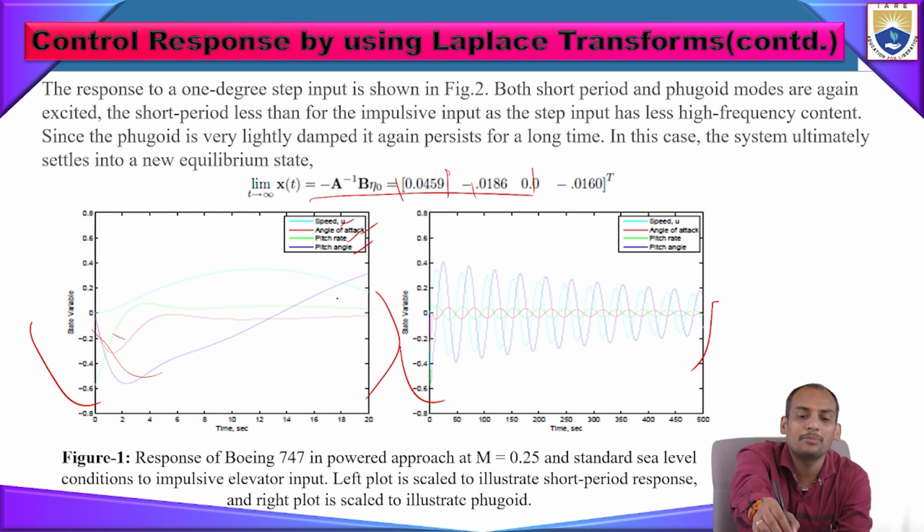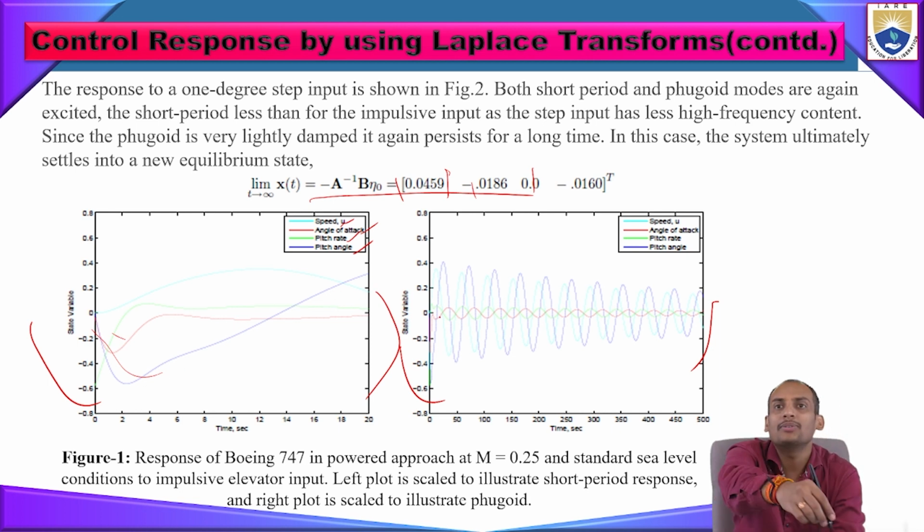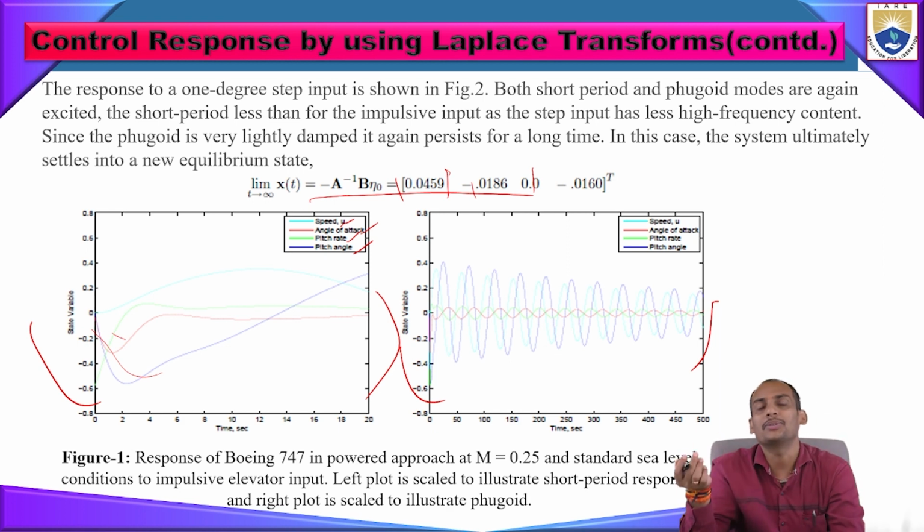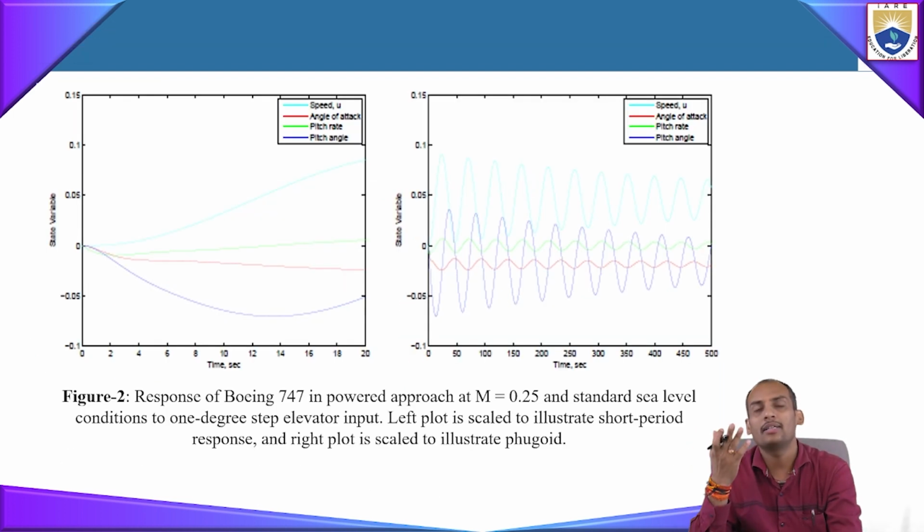That frequency response, the trend of those curves, is what we have plotted. These are all MATLAB generated curves. You can try this by writing a MATLAB code for the above equation and matrix, or by solving it using the MATLAB Simulink integrator module, so that you can get this frequency response easily.